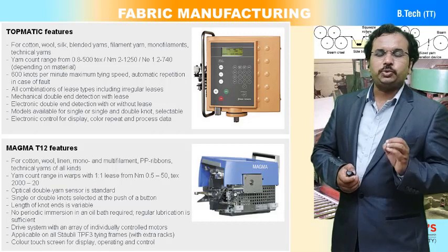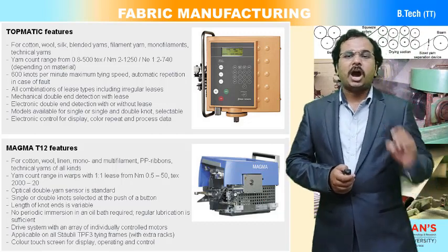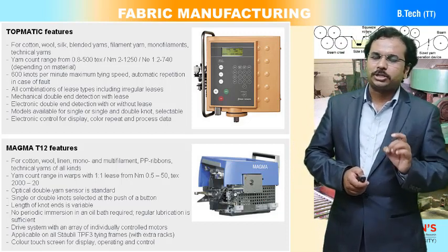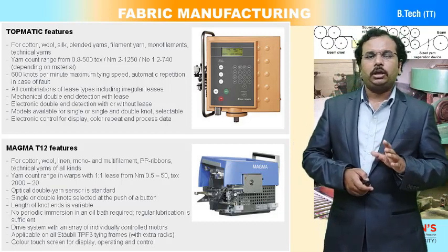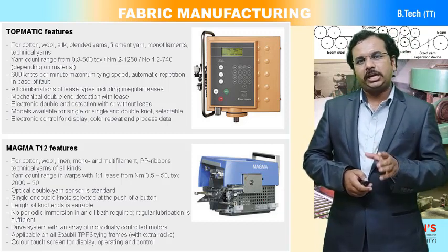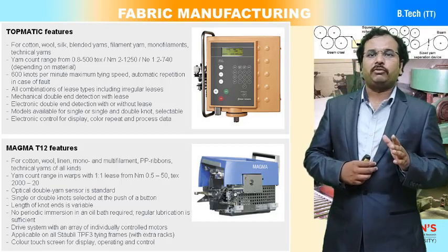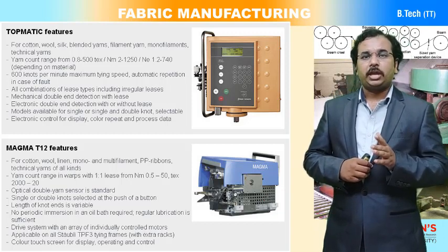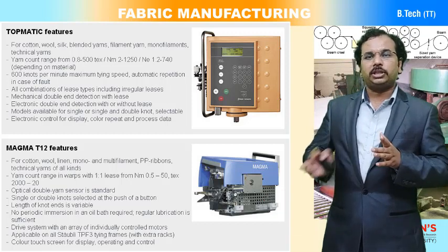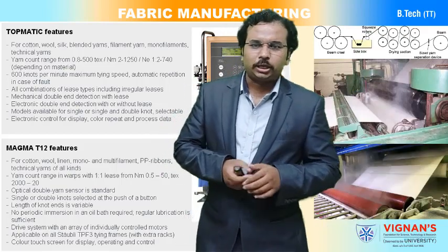Okay. So that is why, if the ordered quantity is large or the fabric is in mass production, in that case we are going to select the knotting process instead of drawing in and denting, if the quality of the warp beam running in the weaving and the new beam produced in the sizing are the same.